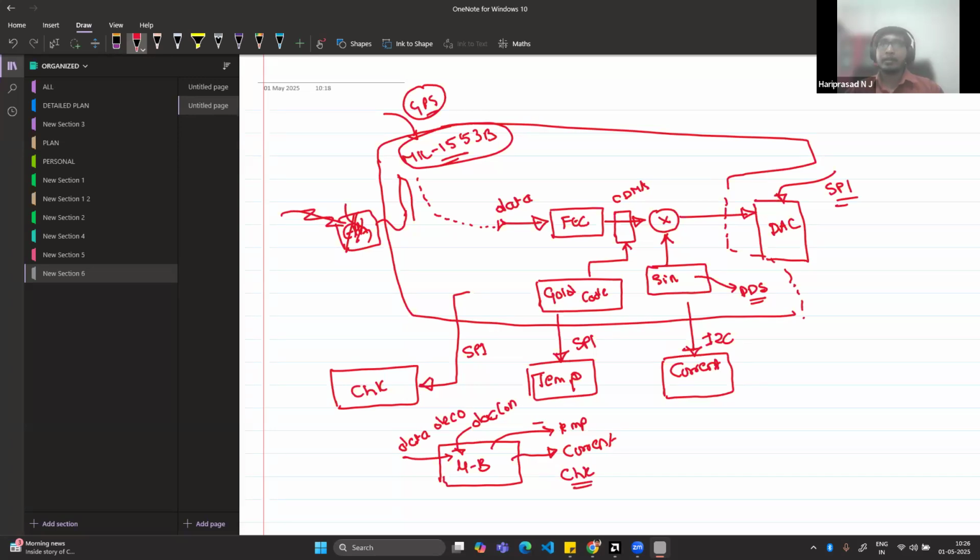I was telling you that accelerometer or GPS, all these things I can put on the software side because that is not a data critical thing. Data decoding, or the command line RT interface, I can put on the software side. But the actual data I'm getting, I cannot put into software. It has to be processed at higher speed because that impacts my throughput.